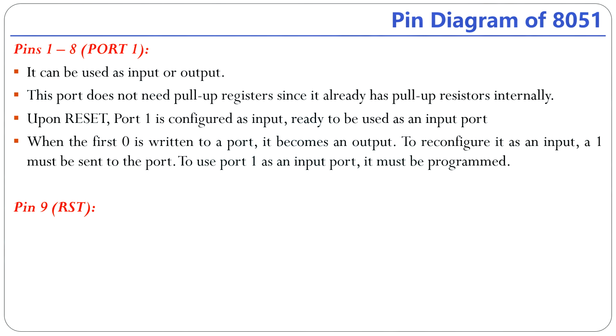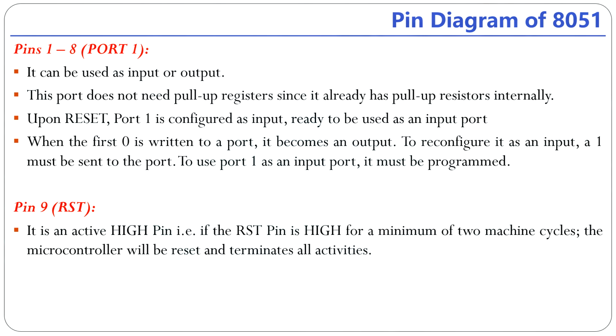Then the reset pin. It is the ninth pin. It is an active high pin. If the reset pin is high for a minimum of 2 machine cycles, the microcontroller will reset and terminate all internal activities.